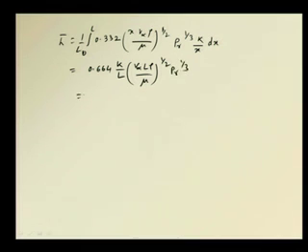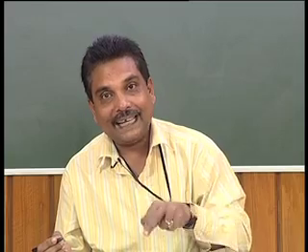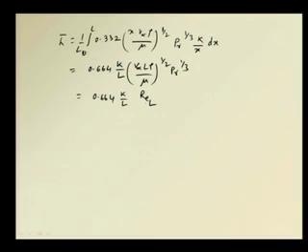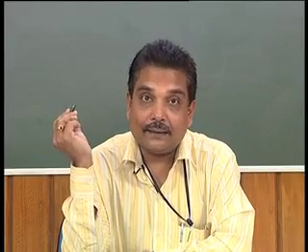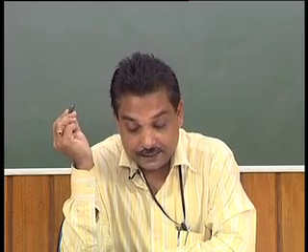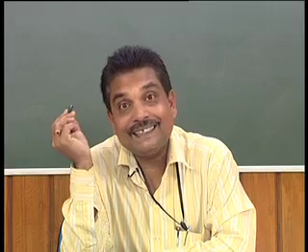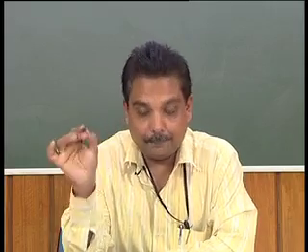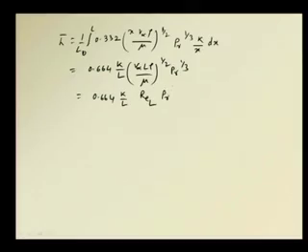So, this is becoming actually 0.664 k by L Reynolds L. Now, here x is replaced by L. So, it is becoming the Reynolds number with respect to length of this. So, this is the Reynolds number at x is equal to L. So, we should be very careful. The average value of the heat transfer coefficient we are getting when the Reynolds number value is calculated based on the length of the plate, and Prandtl to the power 1/3.